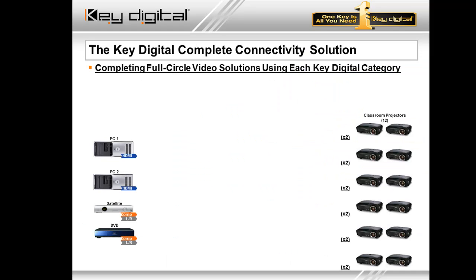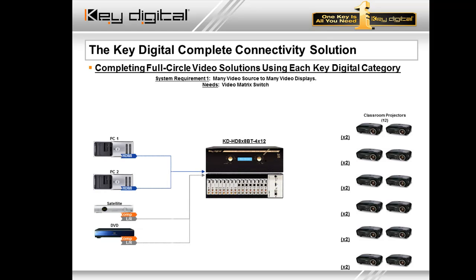So we know the matrix is now in the digital realm. And let's not forget the goal in mind here is delivering the entire system. To deliver that entire system, you're no doubt going to need some peripheral devices to complement that matrix. So as a recap, here's a system here that has many video sources that are needing to go to many displays, which of course is the epitome of a matrix application. Now, we have a problem here with this system, which is two of the sources, as you can see, are component video. They are component video sources that need to go into an HDMI system.